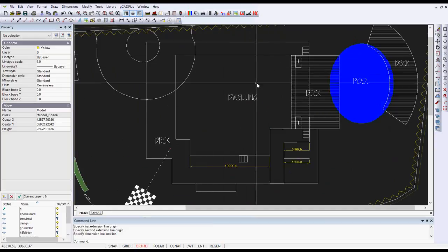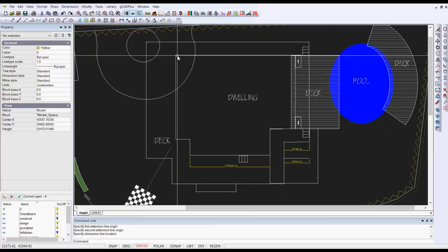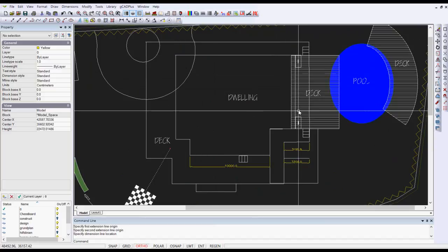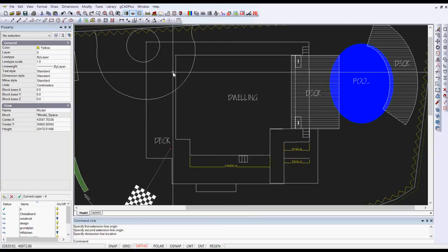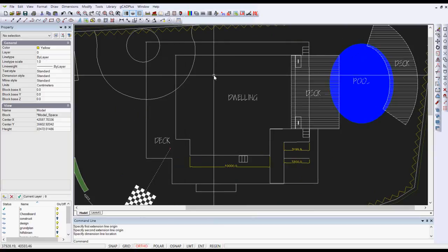You would have been on site, made a mud map, just start at one corner, put ortho on and move your way around the drawing, and ultimately it should close with all angles being 90 degrees, unless of course the architect has some other angle in the footprint at some point. So it's quite important to keep an eye on those things, because once you want to apply dimensioning, things can be just a shade off.